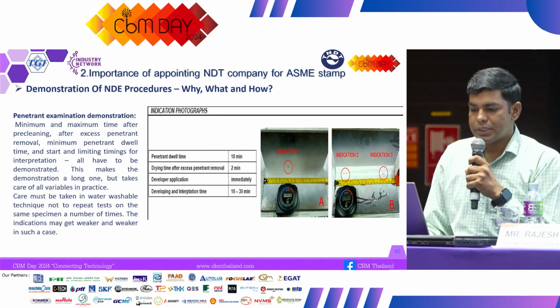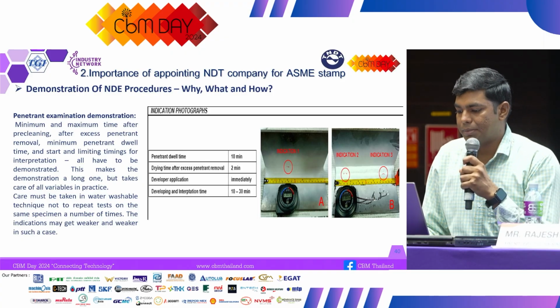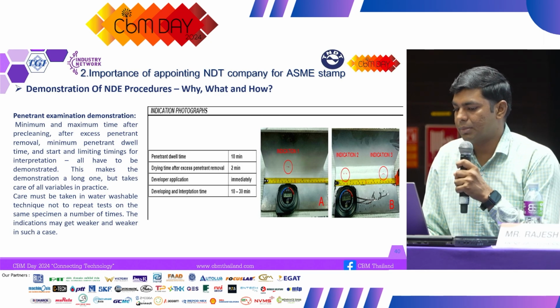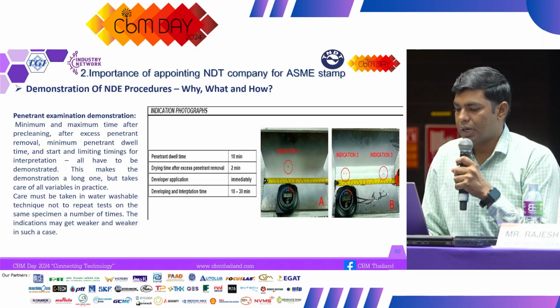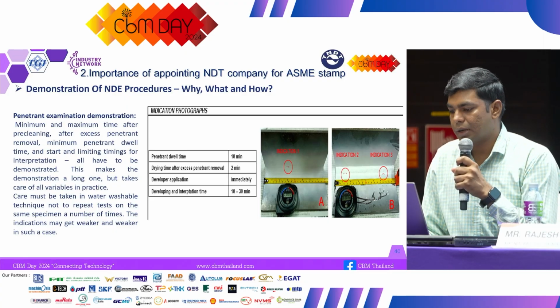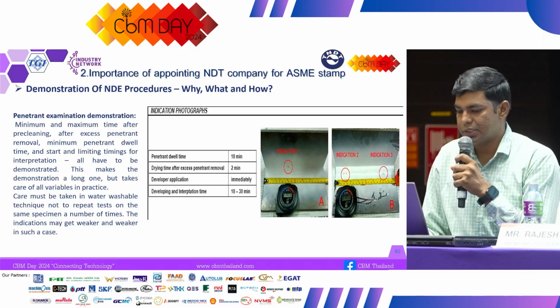So this examination has a maximum and minimum time after pre-cleaning, excess penetrant removal, minimum dwell time, time start, limit timing, and interpretation time. All of this is important in PT. Some have a minimum dwell time of 10 minutes and a dry time of 2 minutes, after which the developer can be applied, and then everything is observed, like these indications.